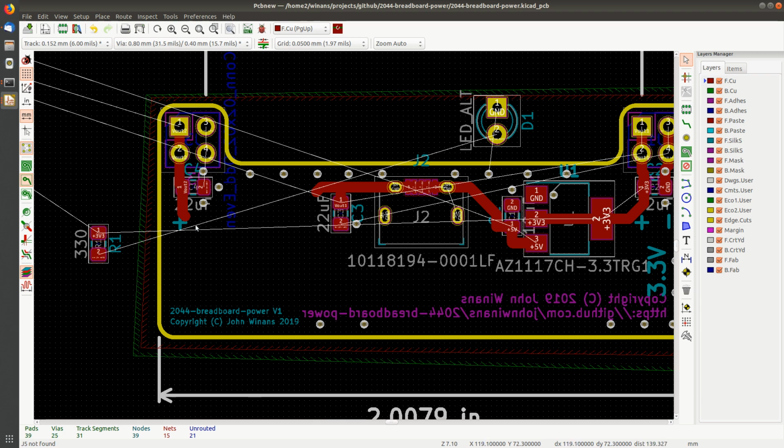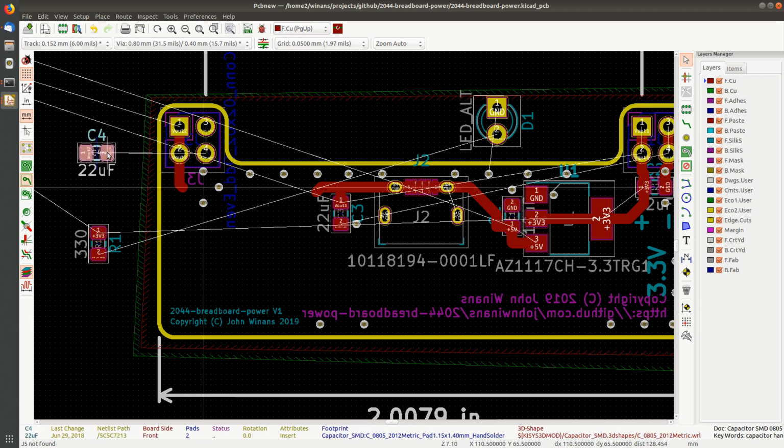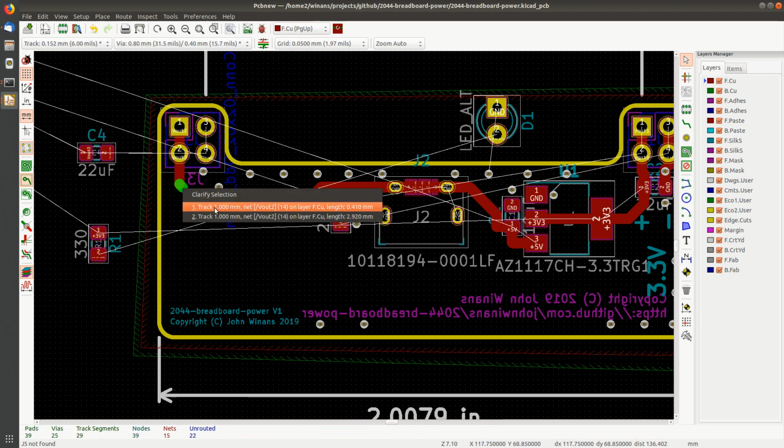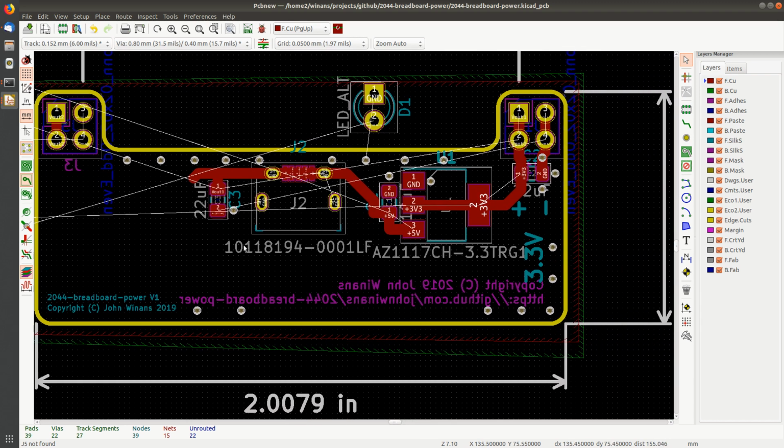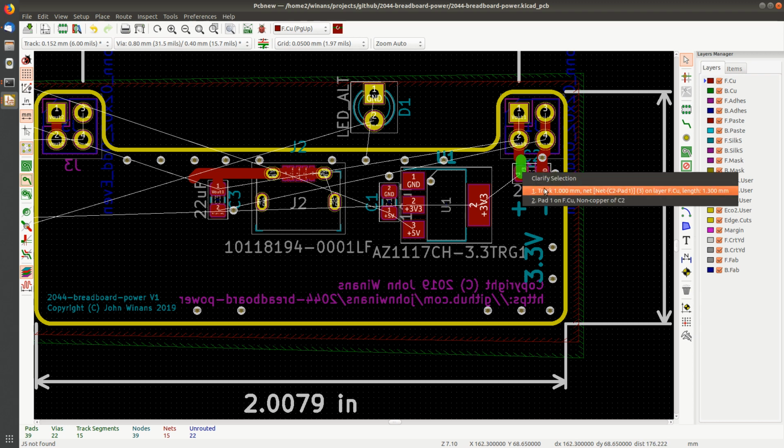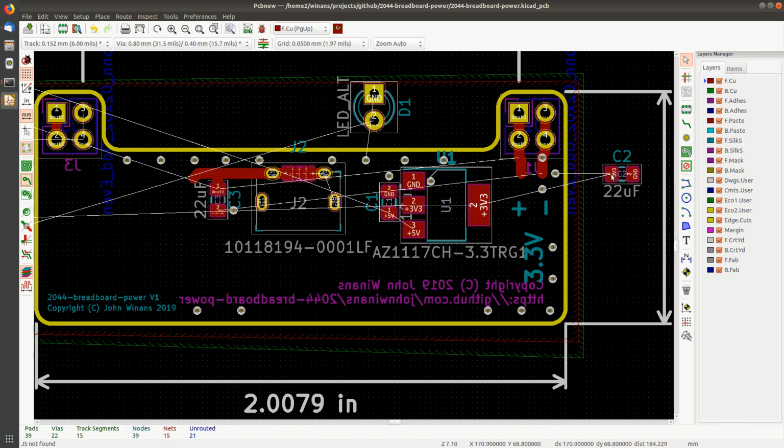We're going to redo. Certainly, it's not going to say 5 volts there anymore because the headers are going to be selectable, right? And we've got to select which track to delete, and delete. We can save some of the vias. Let's go ahead and delete the track, delete the track, delete tracks, delete that track, delete this track, and move this part. Come on. Get that out of the way.